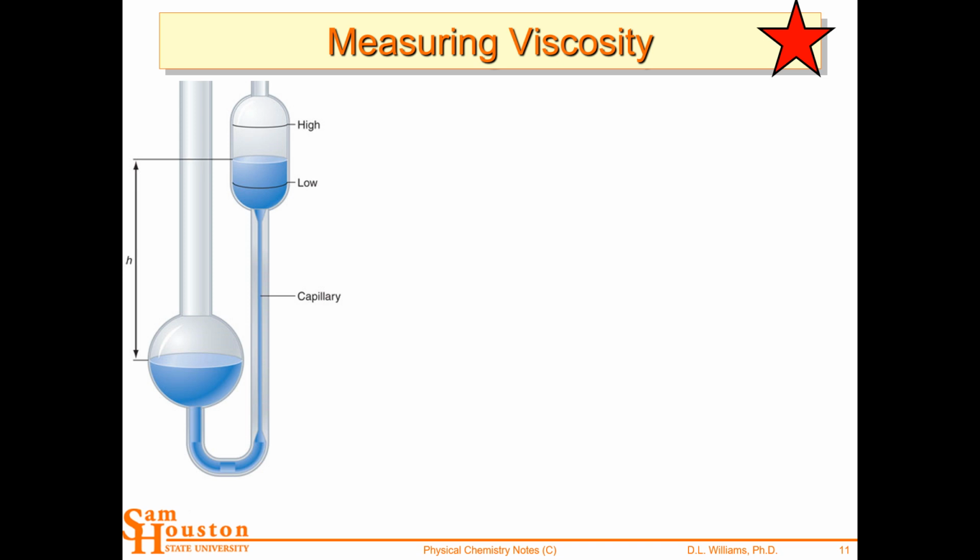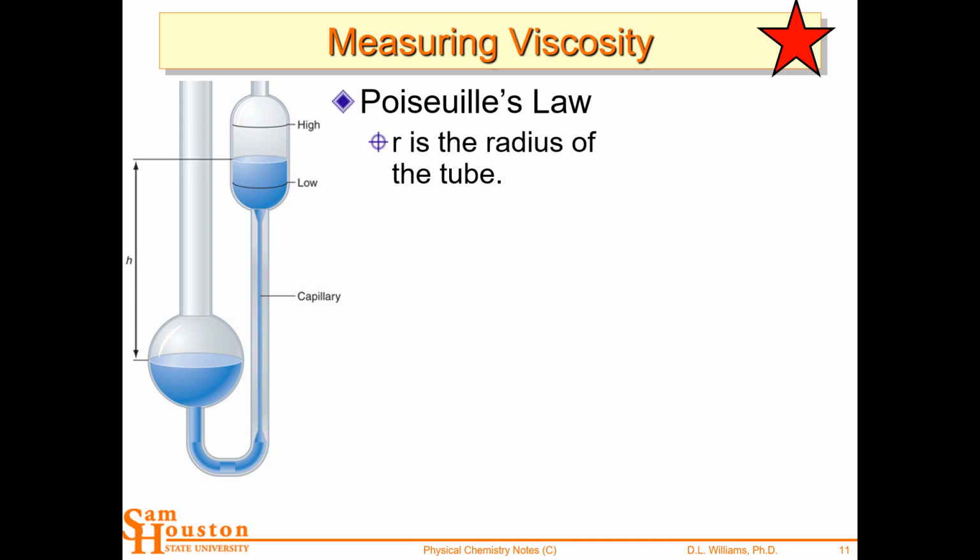So if you're talking about a motor and you're talking about pistons, you've got a certain frequency that oil has to be able to maintain a certain flow characteristics, and so you would want to know the frequency dependence of your viscosity terms. And you can get that from a rheometric instrumentation. You can't really get that from the falling ball or the Ostwald viscometer.